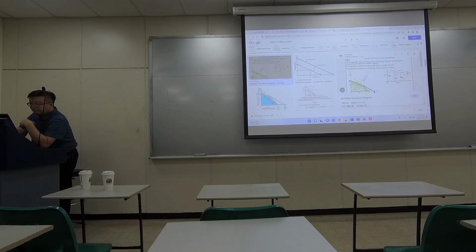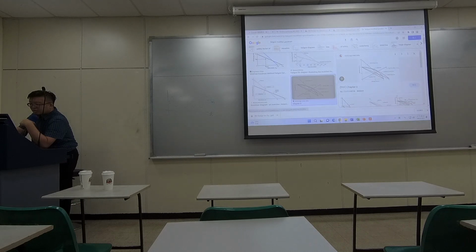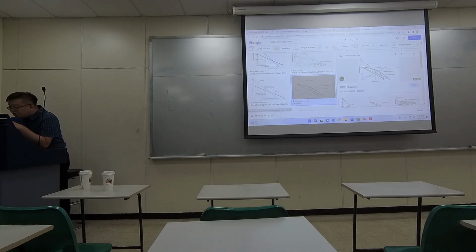in fact, if you keep on searching for other models, I think this one is a good example. Actually, this is a figure from the same book, Soderberg. Over here, there's an elliptic line, and also some line called Gerber. So they are like a curved model.